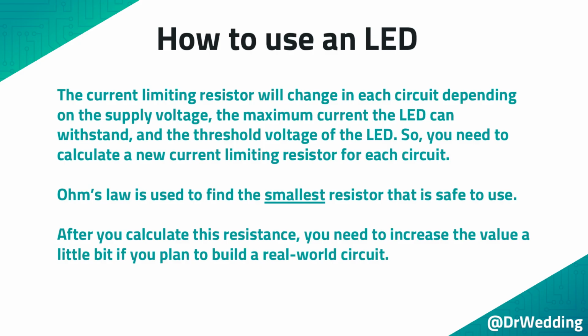Ohm's law is used to find the smallest resistor that is safe to use. After you calculate this resistance, you need to increase the value a little bit if you plan to build a real-world circuit.